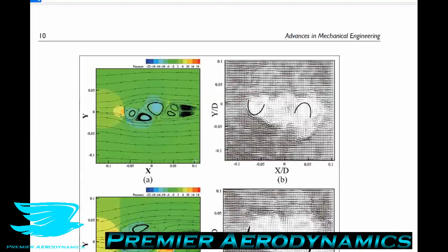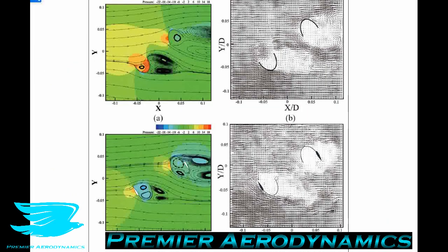The flow physics is shown in figure 12 for this angle. Let me scroll down to that now. Here we go. Here we not only get significant differences in the pressure distributions, but also in the general flow fields, both the CFD and the PIV. Firstly, the pressure on the upstream blade is completely different. For the drag only blade, we see a high pressure of about 14 pascals, just here in the blade cavity, while for the lift and drag blades, we see the exact opposite, -14 pascals.